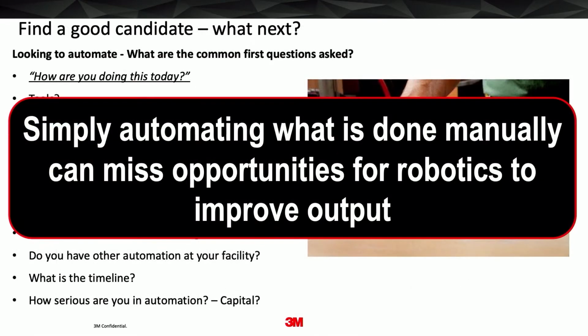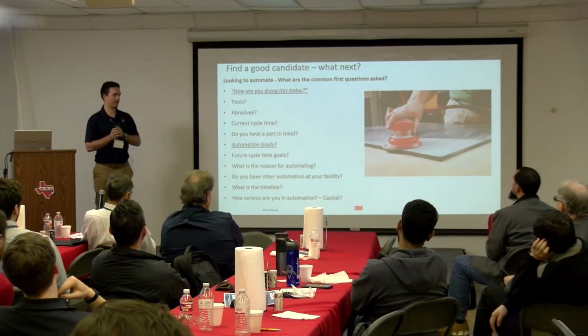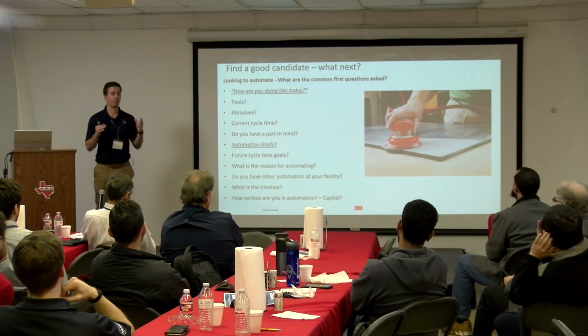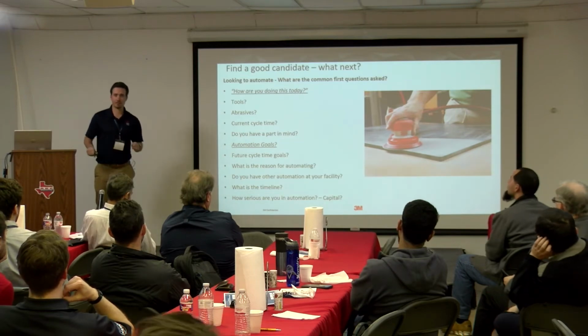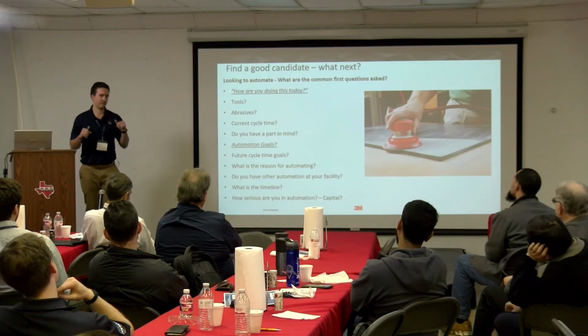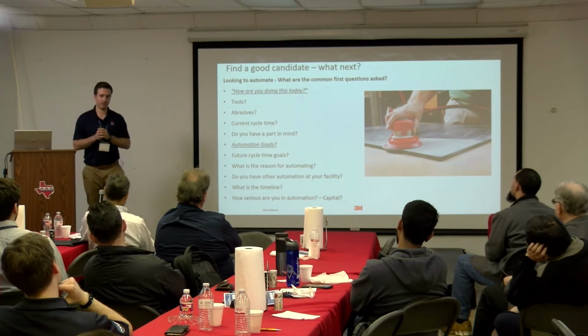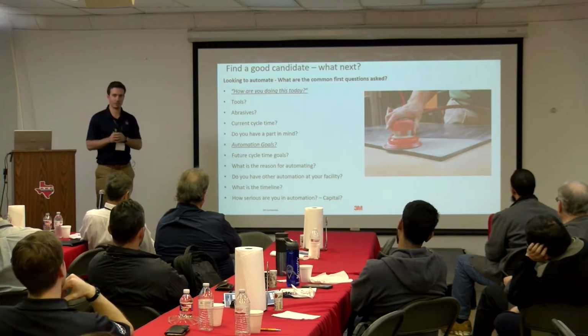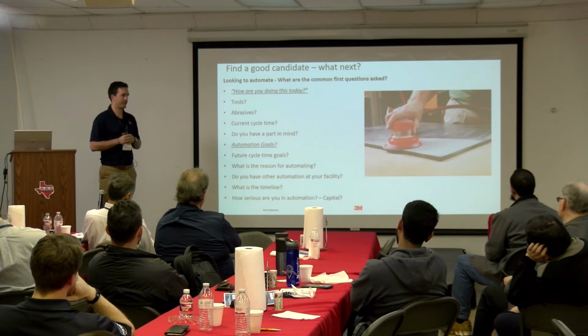The biggest question that inexperienced integrators will ask is, how are you doing this project today? I can stand there and look at an operator, see what they're doing. If they're doing weld grinding, for example, a lot of back and forth to remove the welds, the inexperienced integrator will try to just copy that. They'll look at how to remove these welds without changing it up, using the same exact tooling. We like to step back and figure out why they're doing what they're doing, so we can implement robotics to show the value of robotics rather than just try and copy something.